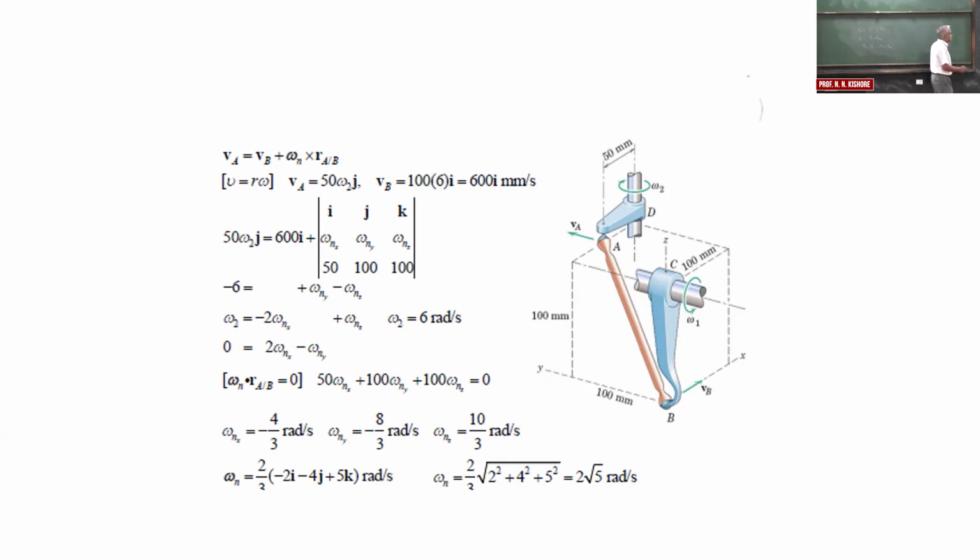The thing you have to observe is that just like in 2D we have pin joints, here we have spherical joints, like cup and ball. That means it is free to rotate, because that kind of freedom is required. You have a cup and ball arrangement in the joints at A and B. So what is that freedom?